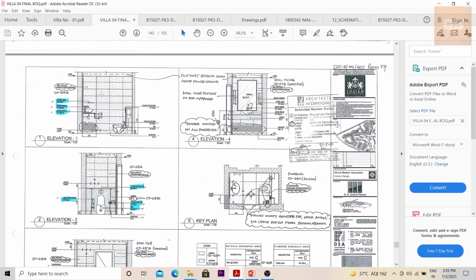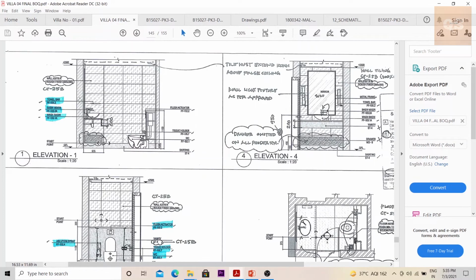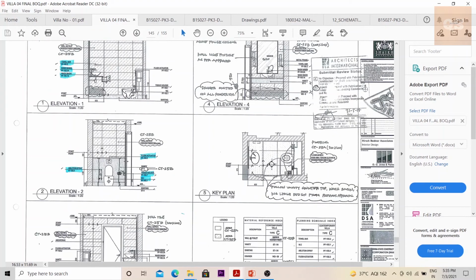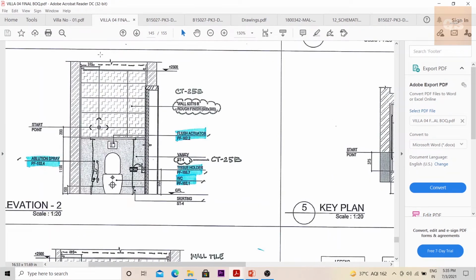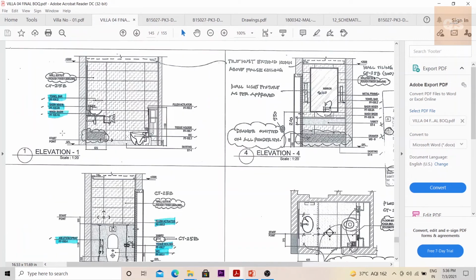Now this is another elevation drawing, of your toilets. Usually you cannot measure the vertical pipes of your toilets or your plumbing system using the plans or layouts. For that purpose, you can use this elevation drawing. From the plan layout you get the horizontal pipes, the measurements of pipes coming till here. But how far they will drop can be found out using these drawings. You have all these measurements given. From these measurements, you can understand till what vertical distance this pipe is going to drop in all your toilets. You can find that out using these elevation drawings.